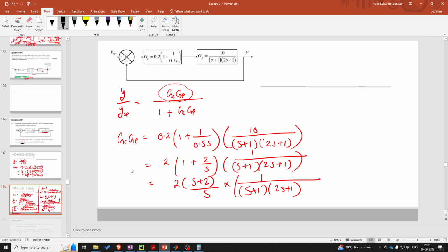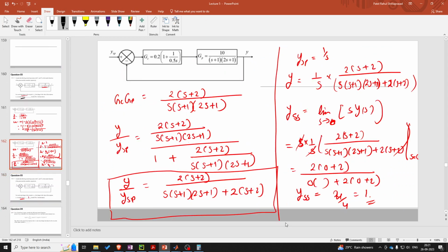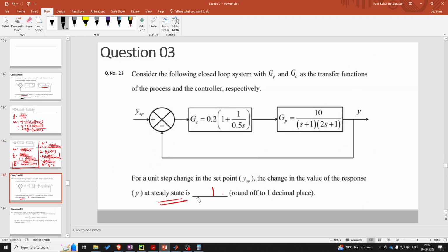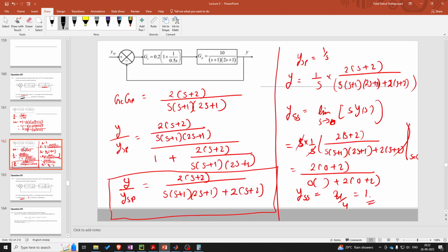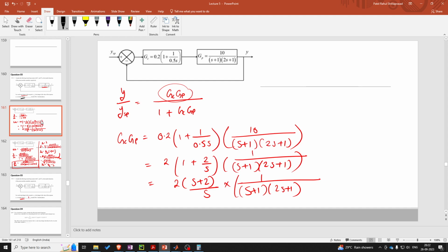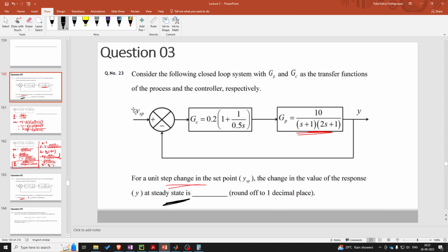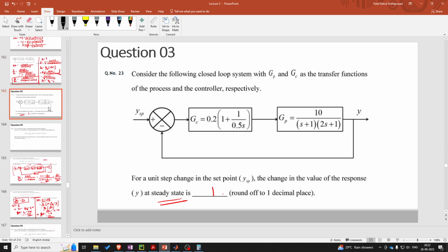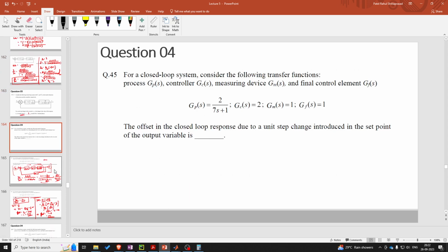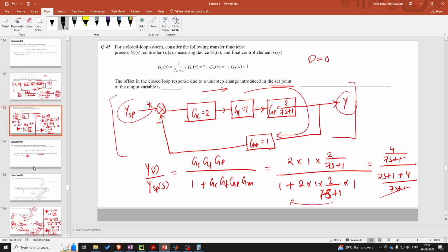Okay. So yes, the final value that I am getting from the actual solution is around 1. So the steady state value after the step change is 1. So in this question we specifically looked at how to use this block diagram representation to find the transfer function, and then using that we found the final value of the system. So now let's try solving questions related to this root stability criteria.